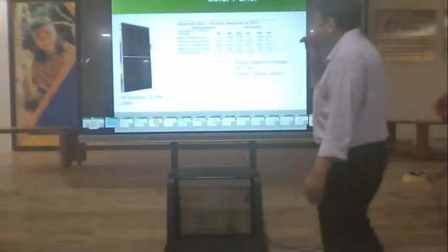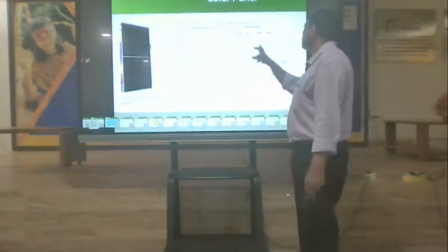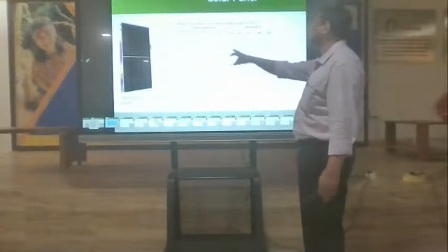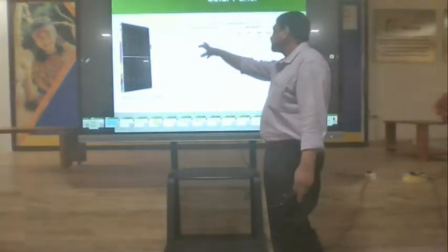Okay. So again, when this is open circuit, you have got a voltage of 48.92. All the cells' voltage that is connected in series parallel, if you have a combinational effect, that is going to be 48.92. That is called VOC, the open circuit voltage. So each panel has got a V open circuit. Now there is certain maximum.